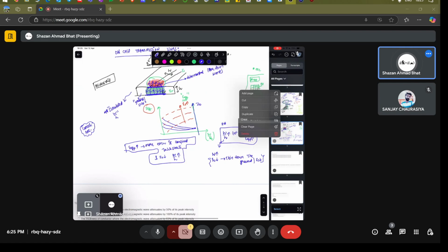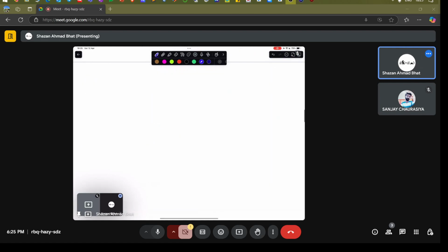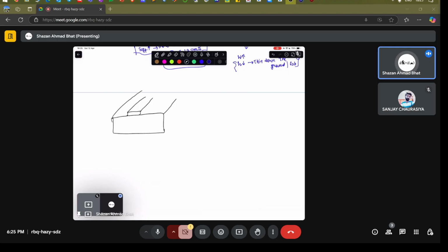And now, if you talk about the inductance, it comes into the picture in these particular structures, because whenever you have a metallic line and you have currents flowing in these metallic lines, you always have inductances, you have capacitances, and resistance is always there, because these are just like transmission lines. So you have the resistance, the inductance, and the capacitance, and you need to solve those transmission line equations, which we have talked about rigorously in the previous sessions, which even the professor has mentioned in the previous weeks. So we have talked about that transmission line approach.